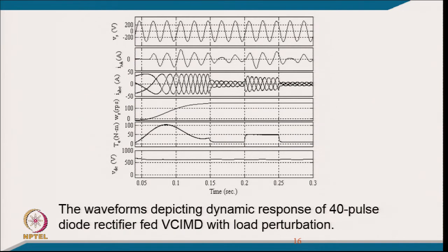I mean we develop it, and this is the typical case when we are feeding an induction motor drive. So, this is the supply voltage, this is the current. During starting, of course, it takes more current from the supply as well as the motor, but once it comes to steady state, almost at no load or little higher load, it draws less current, and you can see the supply current remains sinusoidal as well as balanced.